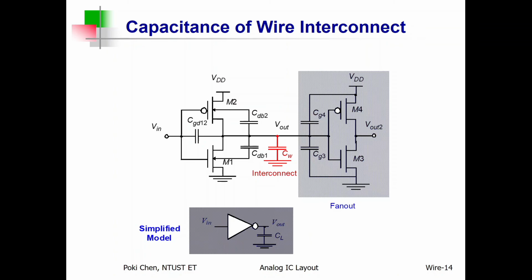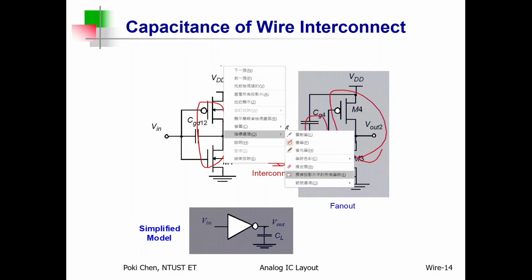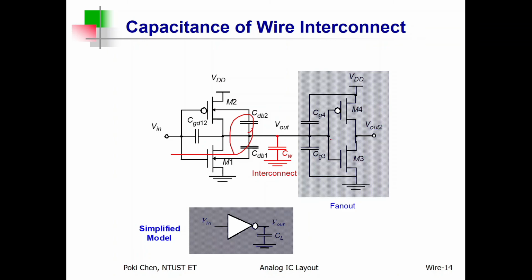So you can see overall how much parasitic capacitance you need to face for such interstage operation between the first stage and the next stage, right? Anyhow, you can see not only the input capacitance of the next stage, not only the output capacitance of the first stage, but also the capacitance of the wire connecting them. All of them need to be counted. Got it? So if you would like to operate this circuit at the highest frequency, you need to reduce all the parasitics. You not only need to reduce the parasitic output capacitance here and the input capacitance there, but also the capacitance of your wires, your interconnections.